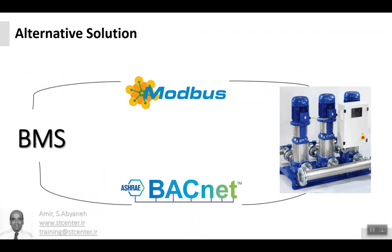This is one way. Another way is that nowadays most of the booster pumps provide us network communication. So we can directly use the gateway in BMS to read the data and write the data through Modbus or BACnet into the booster pump.